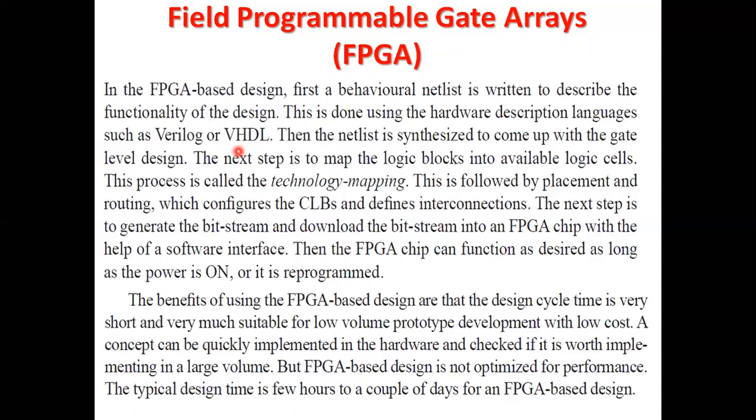We will also be doing the practicals, and VHDL is a language there. We will be learning this language in that platform. Okay. Next, the netlist is synthesized to come up with the gate level design. The next step is to map the logic blocks into available logic cells. This process is called technology mapping.